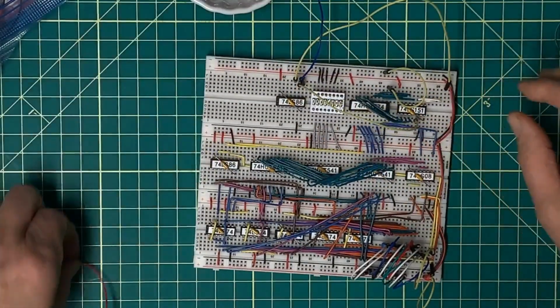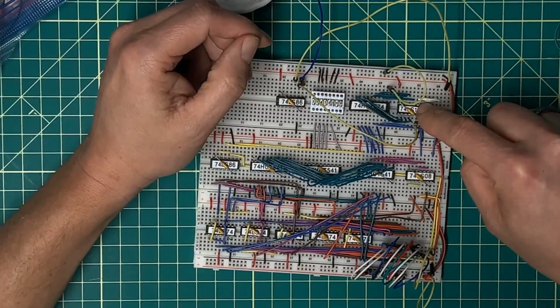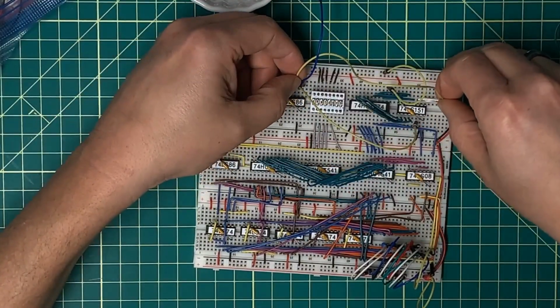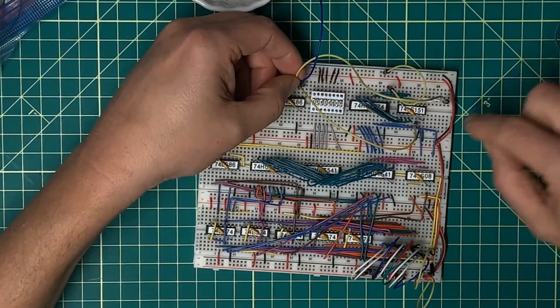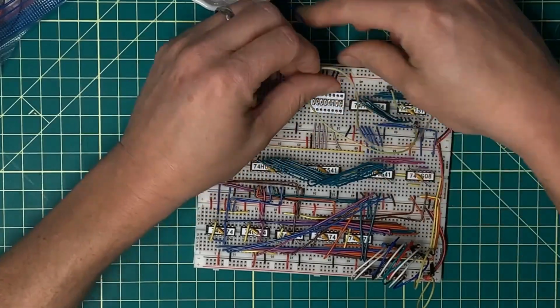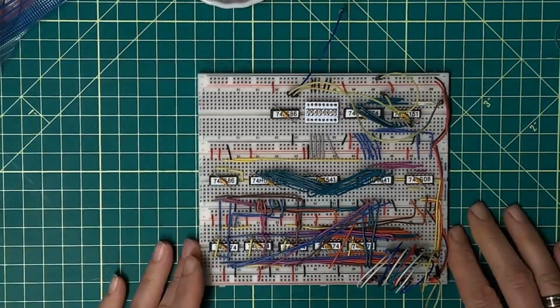This now becomes my instruction suppress. So this is the inverted output off of the multiplexer here that goes into one side of the exclusive OR. My least significant bit of my 4-bit condition becomes the other half of the exclusive OR. And then this is my output, which is now going back off board. Let me clean up those.